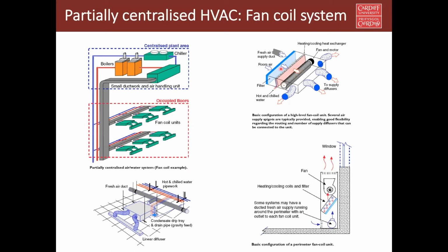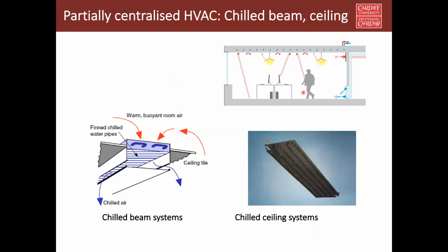Because of that low temperature, the moisture can condense here. And that condensate can be stored in the tray and later on drained. Now that means that it deals with both sensible load and latent load of heating or cooling. So that's efficient in that sense.